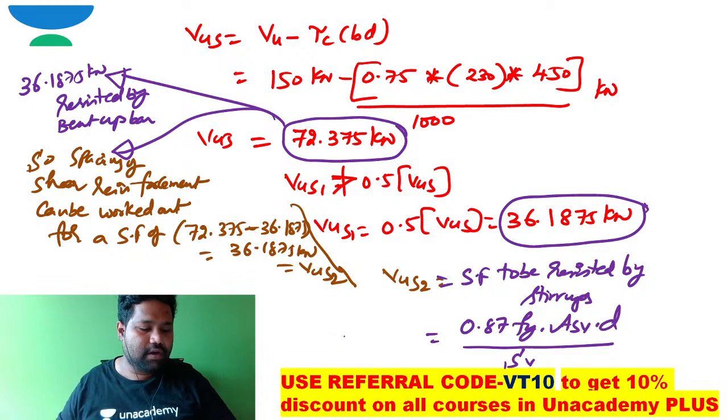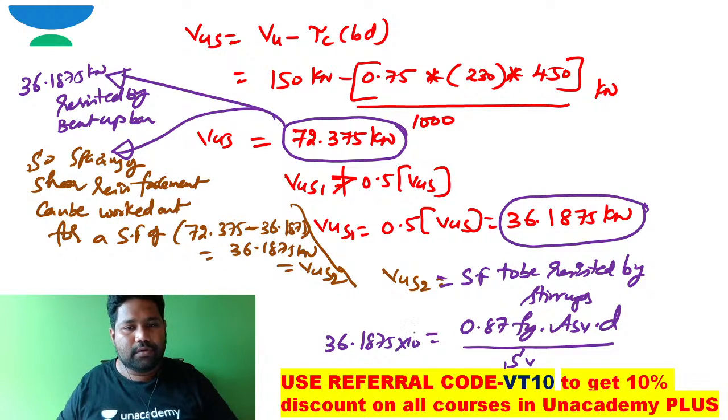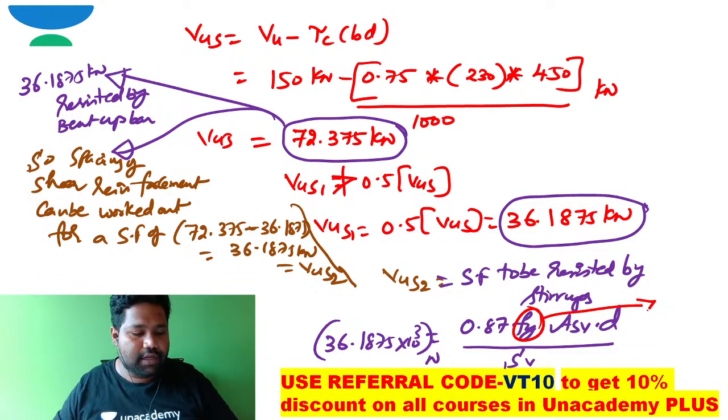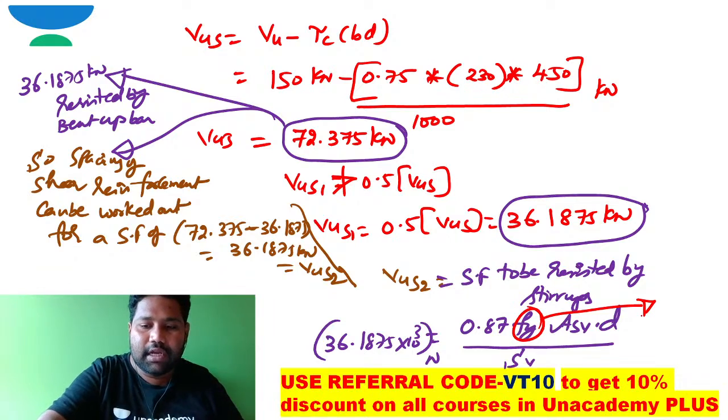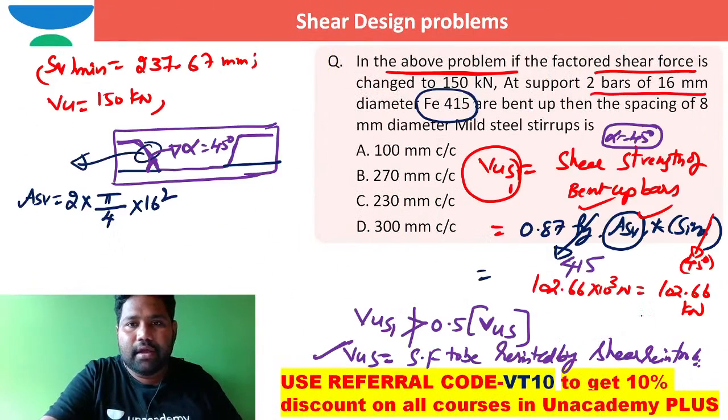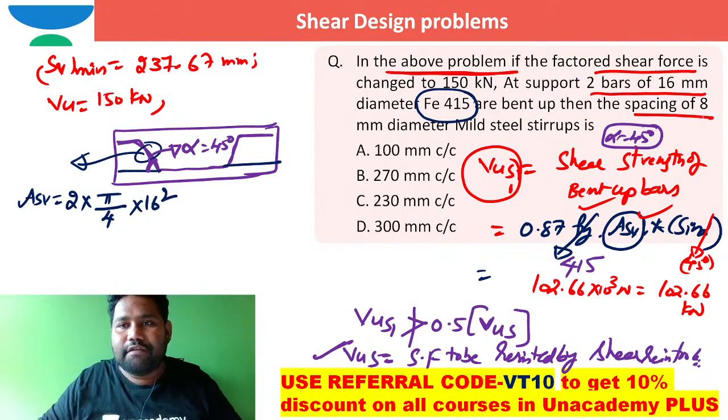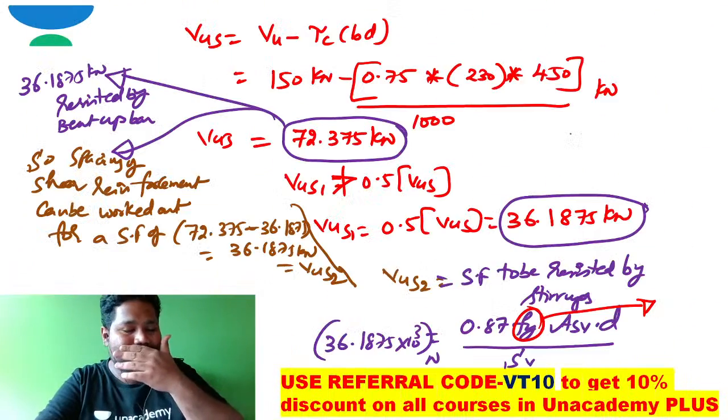VUS2 is 36.1875. And coming to Fy, how can you fix Fy? Fy of shear stirrups is 250, as was given in the problem: spacing of 8 millimeter diameter mild steel stirrups. So the stirrups used are mild steel stirrups.